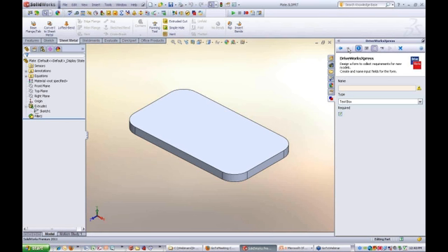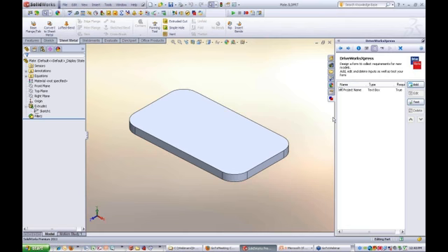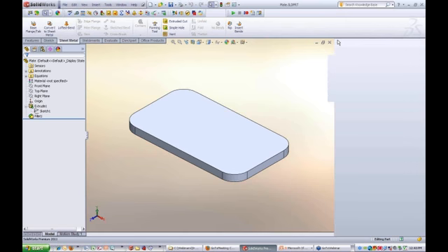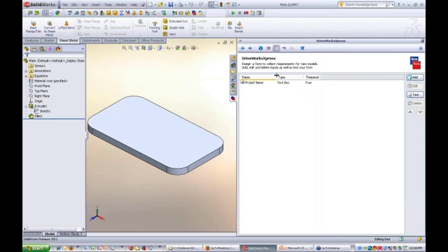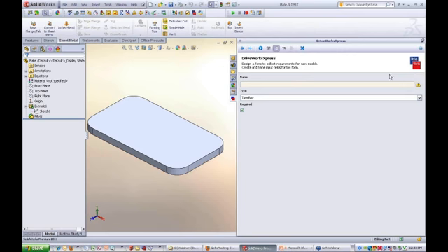Okay, so the name, we want a project name. It's a text box and it's required. There we go, that's better. So now what I'm getting is a field called project name. It's a text box, and it's definitely required to be entered or to have data filled in. We also need to control our plate length, so I'll add another field, and we'll call this plate length.